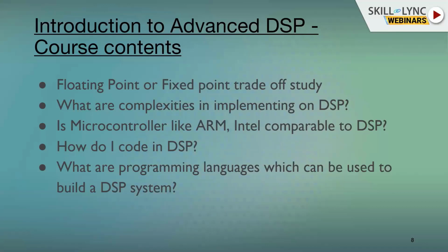It is not going to be used every time, because first, it takes a toll on the performance. Second, even if you're using accelerators, you have to convert the data to fixed point, because fixed point is always recommended for DSP because of the speed and the cost. So 99% of DSP algorithms are implemented in fixed point, except for a few cases where we have to use floating point, and that's only for military purposes and satellite communication.